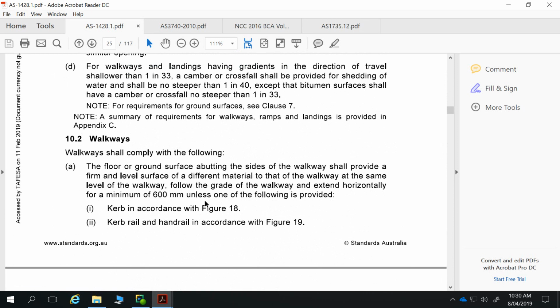It's not going to be possible, obviously, for us to be putting a ramp into this building to have a ramp slope of maximum 1 in 14. We're going to have a very long winding ramp, probably taking a run up from the road nearby to get wheelchairs at that. But it is something that, I guess, we won't be going through today, but it's something that is very important or very handy for you to understand.